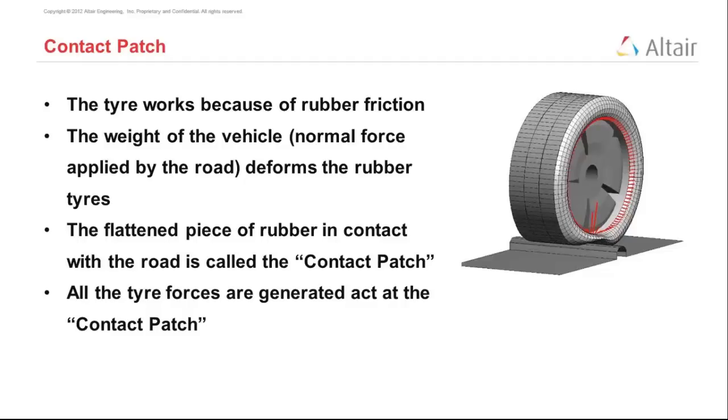In fact, the contact patch is the location, the place on the rubber tire which is in contact with the road. The tire works because of friction between the rubber and the road. The weight of the tire is a normal force that is applied by the road, and that is the normal force that the friction acts on.